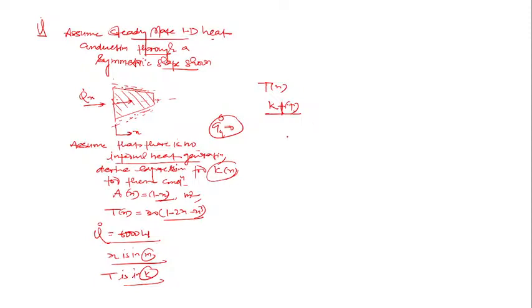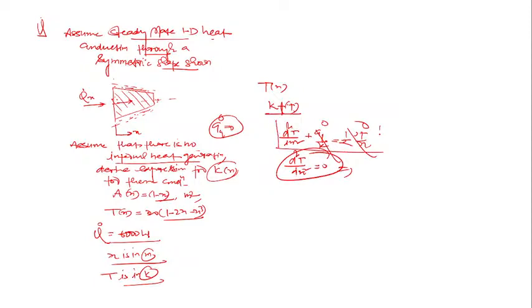I can't use equations like d2T upon dx square plus Qg upon k is equal to 1 by alpha into del T upon del t. Since it's one dimensional with no heat generation, d2T upon dx square equal to 0. We can't use this equation. Why? Anyone? We can't use this differential equation here. Why can't we use these equations?